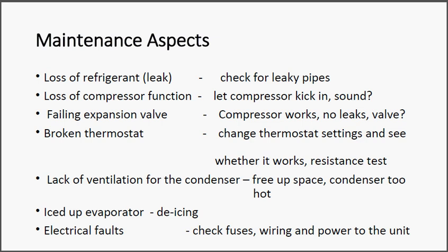It might be an expansion valve, which again is most likely inside the compressor somewhere, that it might be faulty, and then the whole circuit of vaporization and condensation doesn't work too well. Sometimes you get the effect that the fridge on the inside heats up and the outside cools down. If that happens, it's an indication that there's either something wrong with the compressor or the expansion valve. Yeah, that one has just gone dicky or something happened to it. So it can happen.